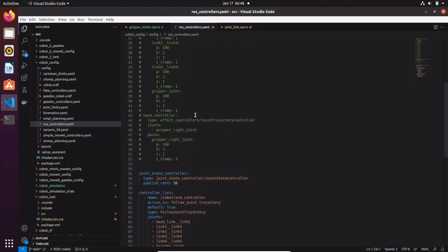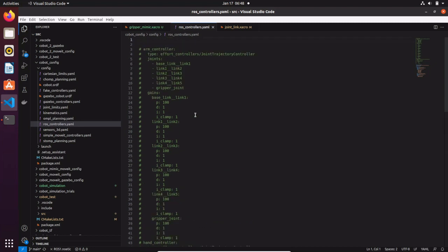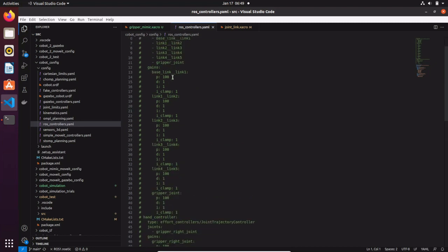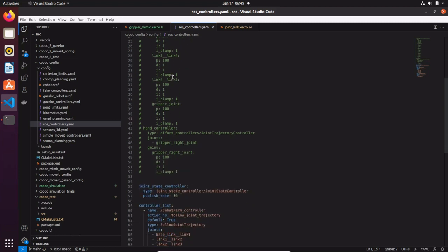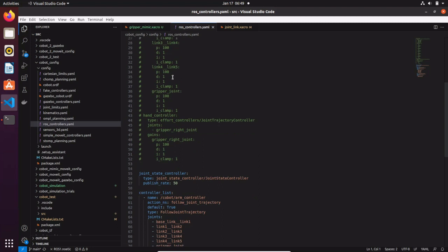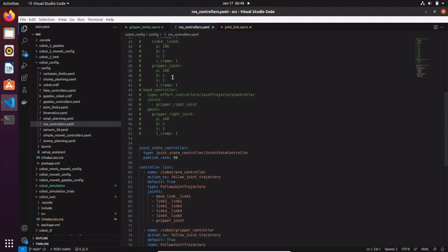I decided to comment it out. Well, we could use it, but it's a mess in the namespace of your robot, and if you use it you risk that the controller manager doesn't recognize your controllers.